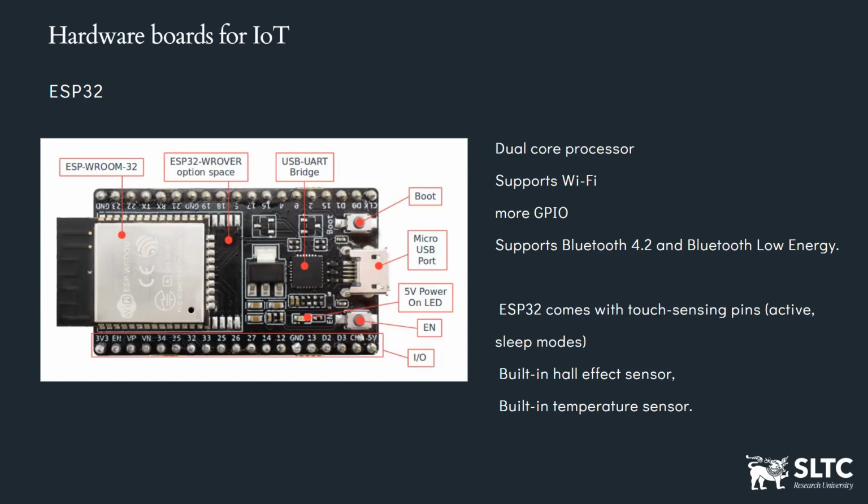So depending on our application, we can introduce the active and sleep modes to enable the microcontroller to only work when the data needs to be measured and processed and so on. So in all the other times, the microcontroller will be in the sleep mode, and that kind of algorithms will enable the microcontroller and the edge device to save more energy.